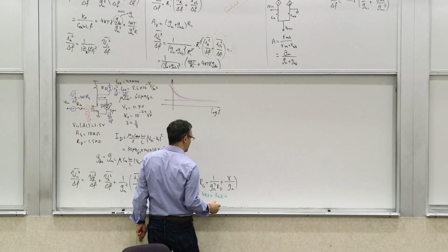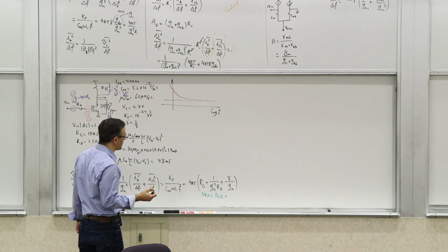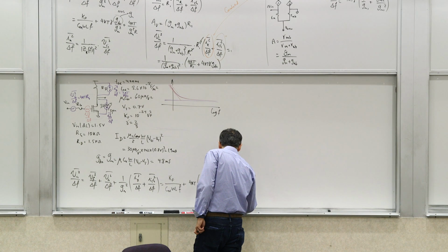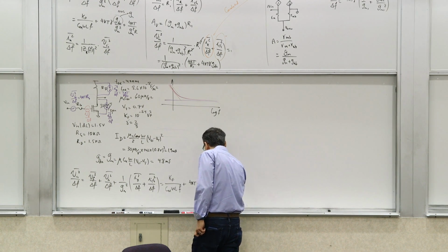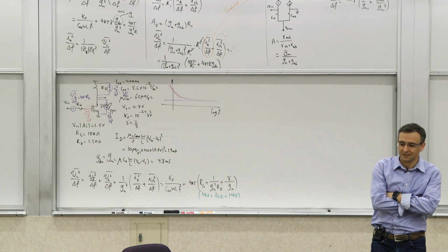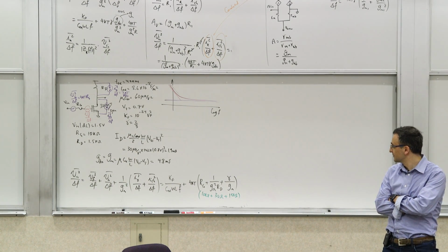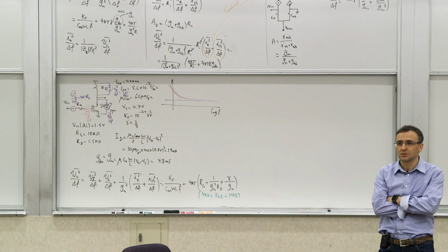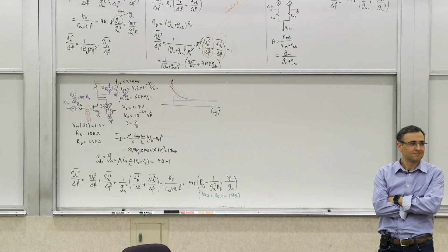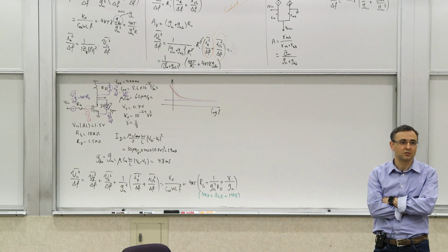And then this one is 1 over, so we said it's 200 ohms, so times 2/3, so it's like, let's say, I don't know, 150 ohms. So what is the major contributor to the total noise? I mean, we can multiply by 4kT, but that tells you which one is the major source of noise at the input right now.